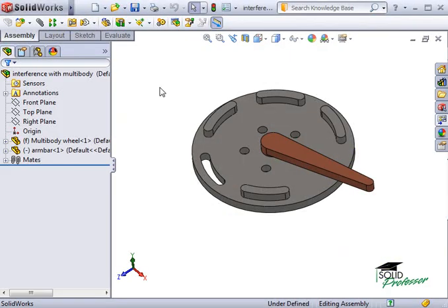If you've ever worked with assemblies with moving components, I'm sure you've used interference detection to help verify your design. SOLIDWORKS has made a simple yet useful enhancement to this tool. You can now ignore interferences with hidden bodies. This is very useful if you create multi-body parts with one of the bodies created for construction purposes only and